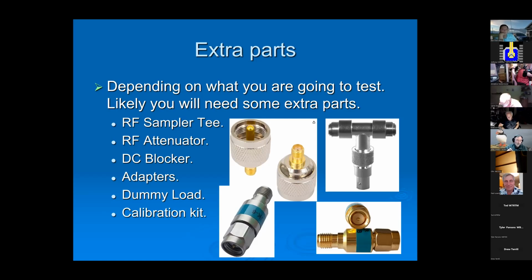So maybe it's minus 10 dB is the best you can put in. Anything past that, if you move up to 5 dB or a full dB, just a plain dB worth of power, that will end up frying that instrument. That's a very expensive mistake. So you always want to think about these attenuators to get the signal down low enough so you understand it before you set the amount of RF that you want to bring into the thing.